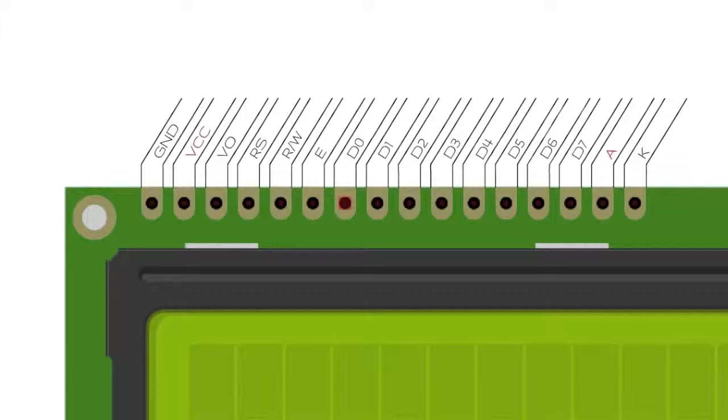Basically, when the LCD is processing information and executing its instructions, it will make pin D7 go high, to indicate that it's in the middle of doing something. When it's free and ready to accept new instructions, that pin will go low. However, you can't check this unless the LCD is in read mode, and for that, you will need to make the RW pin go high.